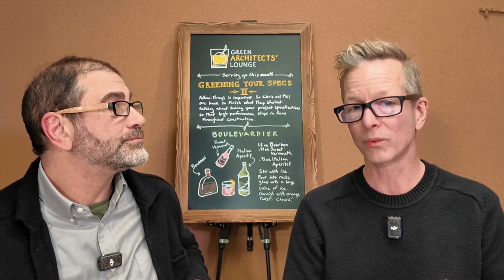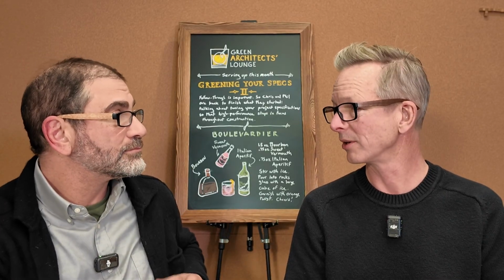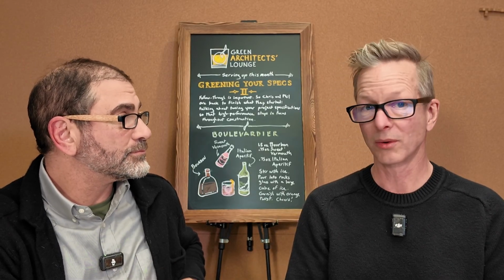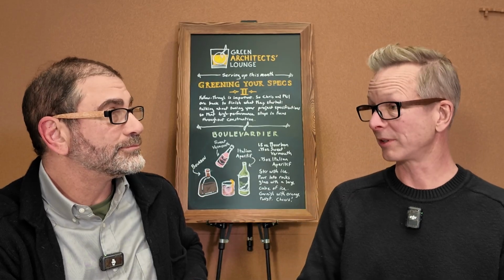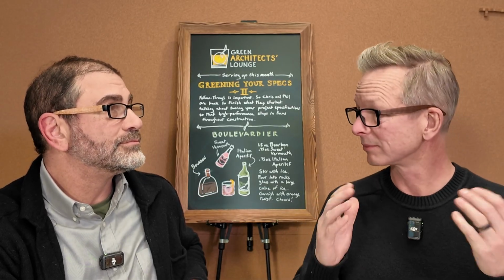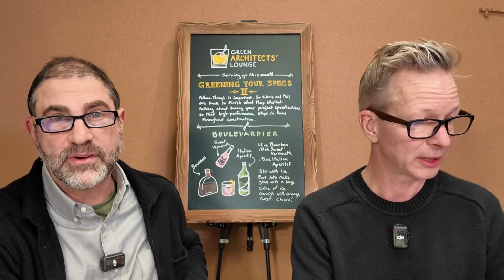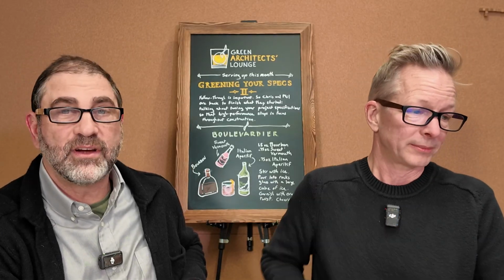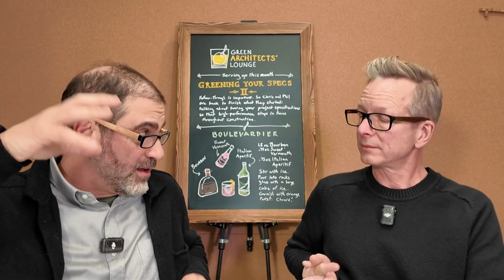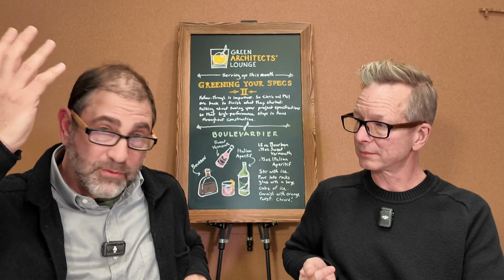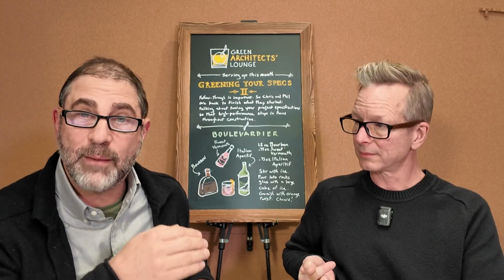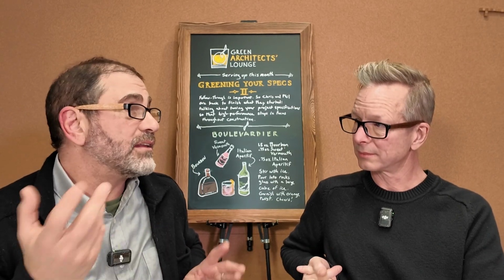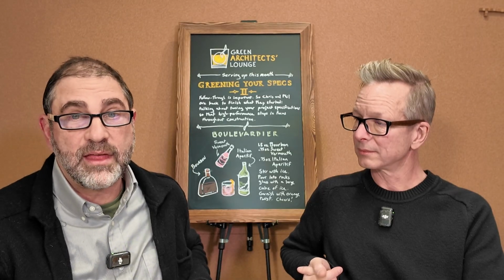No, but you've got to make sure radon is taken care of in your specs. Because if you don't, you've got yourself a legal problem if it happens and you don't have that in there when your building gets built. That's right. Prep for radon. You don't always need to run the fan all the way through the house or the roof yet. You can just wait, cap it off, test it. And if you need to add that fan later, at least you're ready to go at that point.